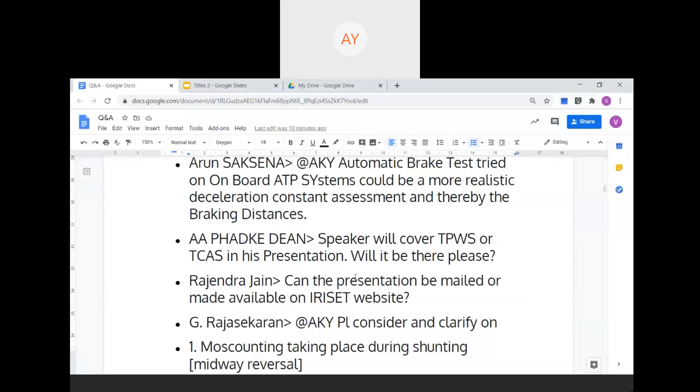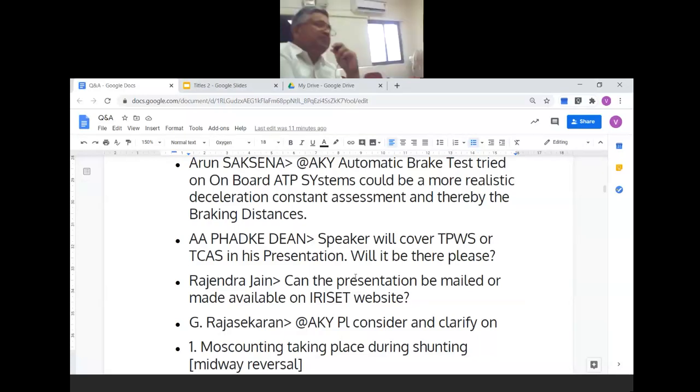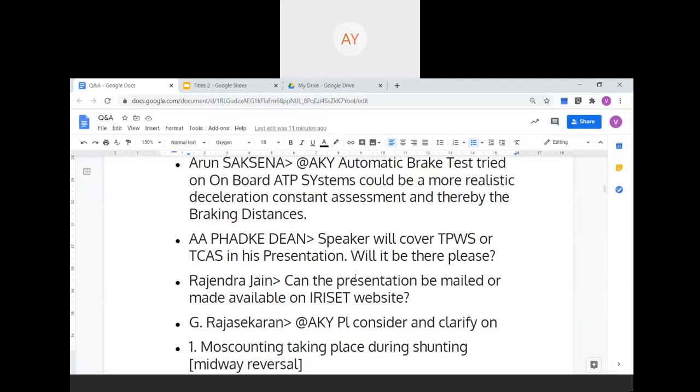Yes, probably so. But all these data-driven systems need a guaranteed limit beyond which calculations should not go. I was mentioning this because you are trying to refer to certain tables, which are also approximations. And if you remember, when we did the ETCS level 1, TPWS, we were having a hit and trial method. That's true, sir. That's why it took some time initially to bring the actual braking curve of the trains in line with the signaling system available on track.